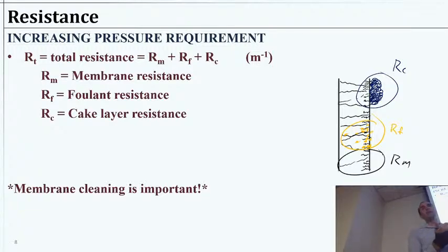But we could describe that as a few components. One would be the membrane itself. Small pores, going to resist the flow. But then we could also have some fouling resistance and distinguish that from fouling resistance in a cake format. When I say cake, I'm talking about particles that are accumulating to a large extent here, right? So what I'll do is I'll highlight these colors.